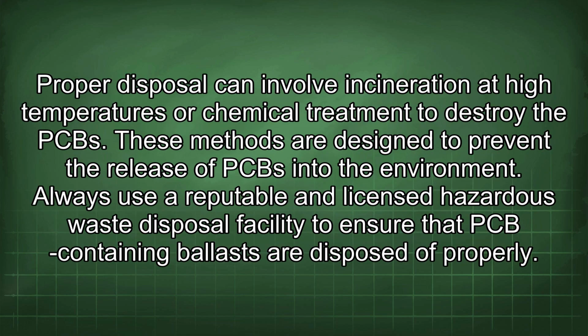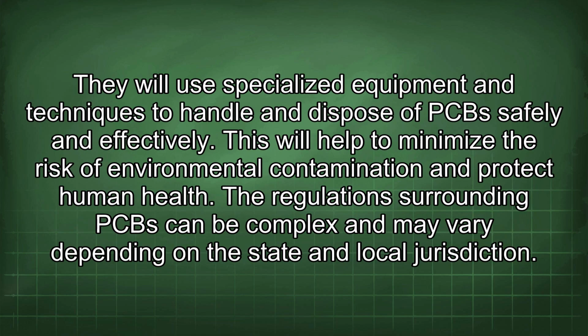Proper disposal can involve incineration at high temperatures or chemical treatment to destroy the PCB. These methods are designed to prevent the release of PCB into the environment. Always use a reputable and licensed hazardous waste disposal facility to ensure that PCB-containing ballasts are disposed of properly. They will use specialized equipment and techniques to handle and dispose of PCB safely and effectively. This will help to minimize the risk of environmental contamination and protect human health.